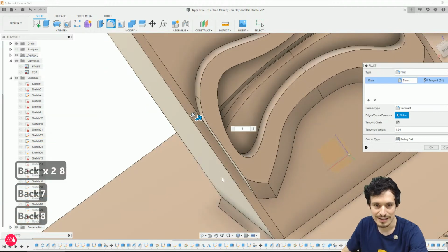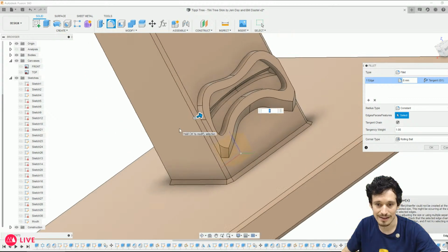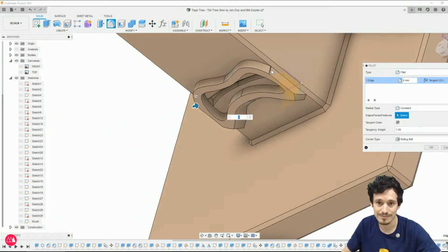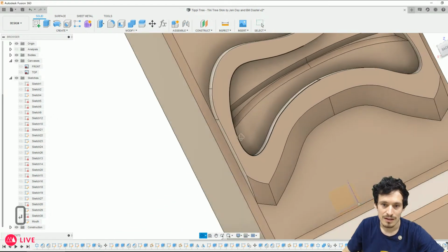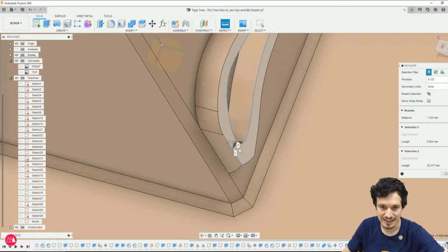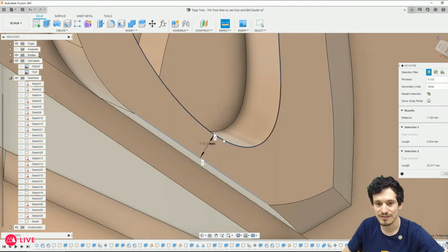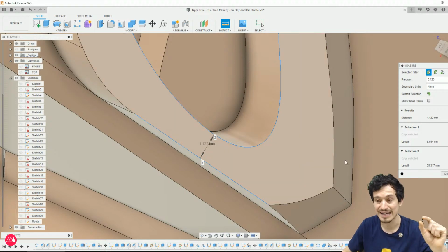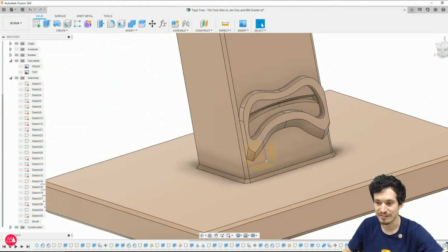This is where you all see that I'm really just messing around and hoping things work out. And oftentimes that works. I mean, the lips get really thin here. That's a problem. I do need to make sure that any thin portion in the z-axis is kind of, well, there we go. It's 1.12. So I'm often measuring things to make sure it's not thinner than 0.8, because then the slicer will have trouble with a little 0.4 millimeter nozzle pulling that off.